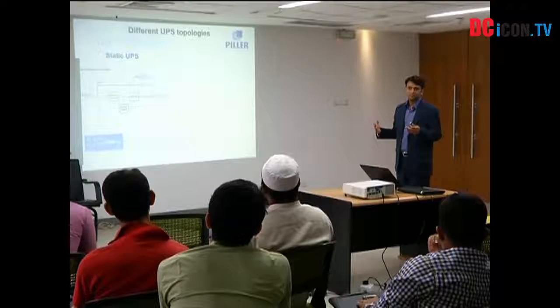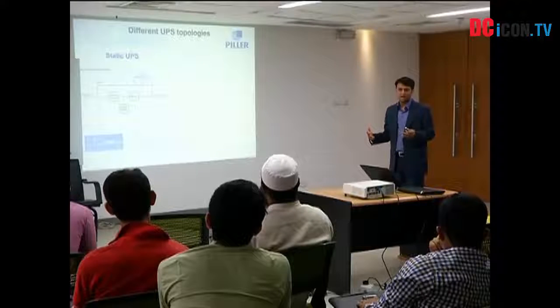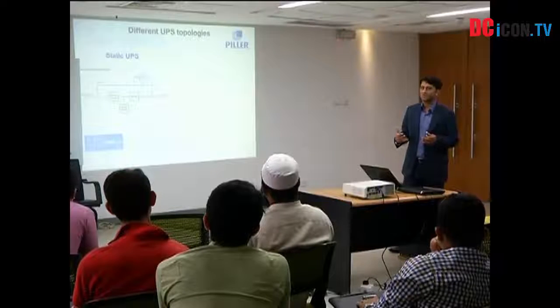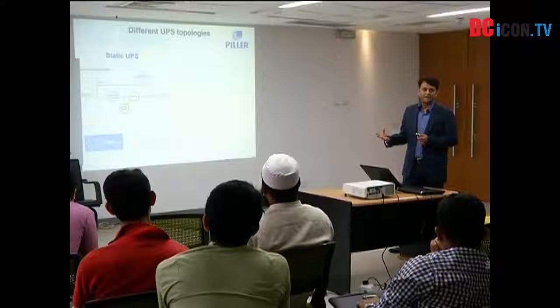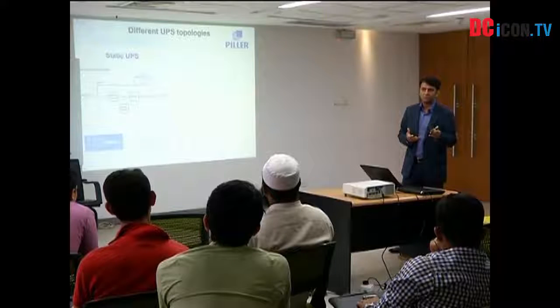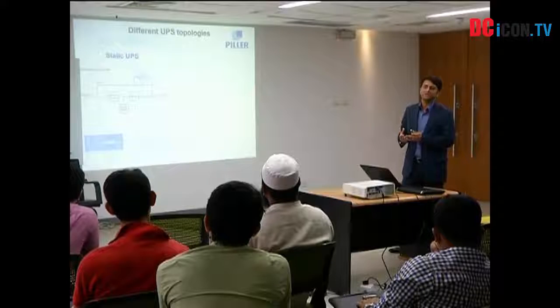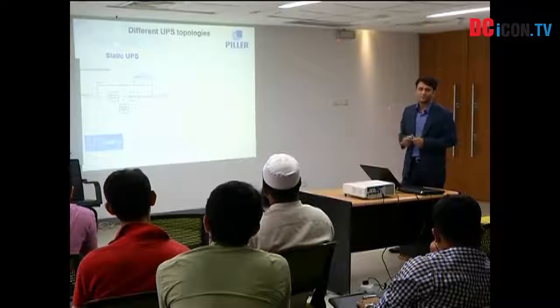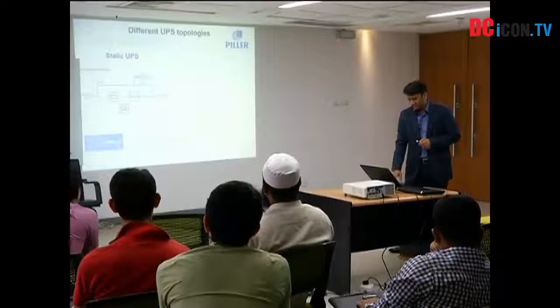So it's called static because there is no moving part generating the output. That's why it's called static. It has nothing to do with energy storage. So if you use a flywheel, which is a rotating part, with a static UPS, it doesn't become rotary. It is still static, but it is with a flywheel. Just a background before we get into the product details.